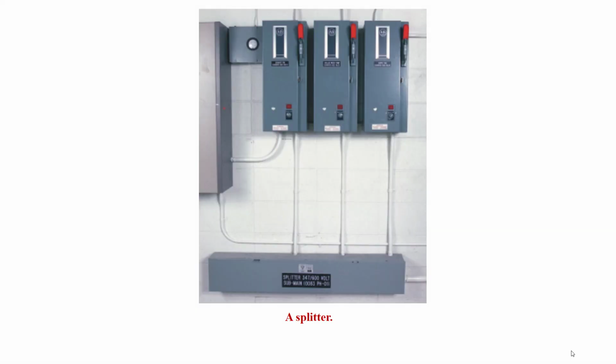So let's begin here. When we're looking at a splitter, we have a feeder coming into that splitter, and then we'll have smaller wires coming off, and they go to fusible disconnects, and then it would go out and feed our load. Anytime we reduce the size or ampacity of our wire, we have to put an overcurrent in. But we have special provisions that allow us not to put an overcurrent at the point where the wire size is reduced if we follow certain rules.